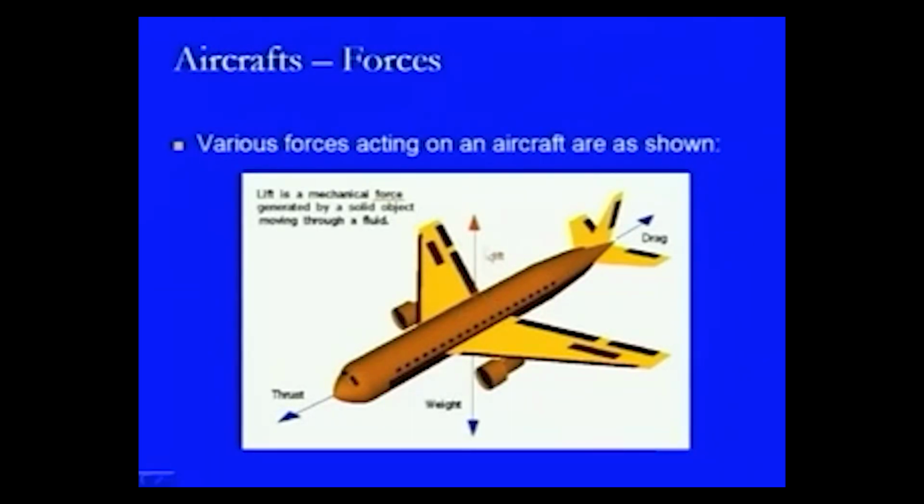This lift is essential so as to bring the aircraft into the air at the time when it is taking speed during takeoff. At that point of time, lift becomes very important, and with the help of this lift the aircraft keeps on moving in the upward direction, and then as soon as the lift and the weight become equal, it takes a horizontal path and starts moving in the horizontal alignment condition.